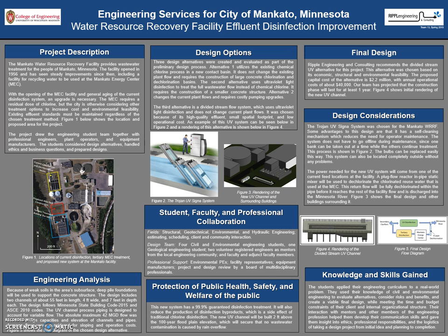This new UV system has a 99.9% guaranteed disinfection treatment. It will also reduce the production of disinfection byproducts, which is a side effect of traditional chlorine disinfection. The new UV channel will be built 2 feet above the 100-year floodplain elevation, which will ensure that no wastewater contamination is caused by rain overflow.